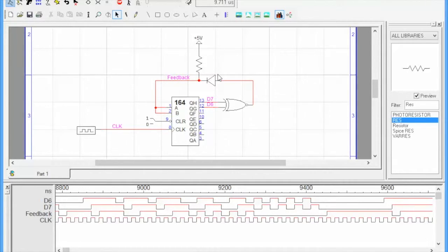Now we can also move a group of devices. So let's select this guy, and then hold down the shift key and click on the resistor, and then click on the open collector buffer. And now all we need to do is drag it, and the three of them will go together. So there, I've dragged those three over to the right. Now I don't really want to do that, so I'll just Control Z to undo it, and it goes back to where it was.